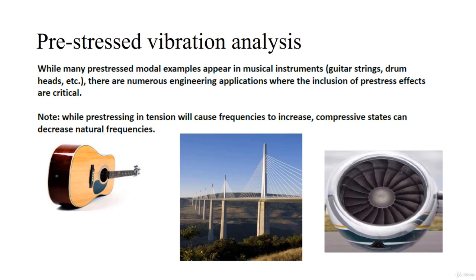Then coming to the next type of modal analysis, which is the pre-stressed modal analysis or vibration analysis. In the previous case, we didn't have any forces applied. But if, in the case of a guitar string, we want to analyze the natural frequency of this particular string, this string is attached to the guitar with some tension. So in order to simulate such cases, we need to perform this pre-stressed vibration analysis.